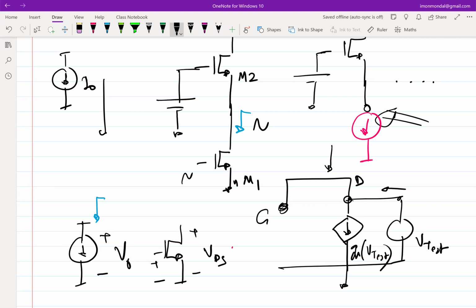Okay, fine. So this is not going to work, but still I want this VGS for the requisite amount of current, and this VGS should automatically adjust itself with regards to any change in threshold voltage or mobility and so forth.